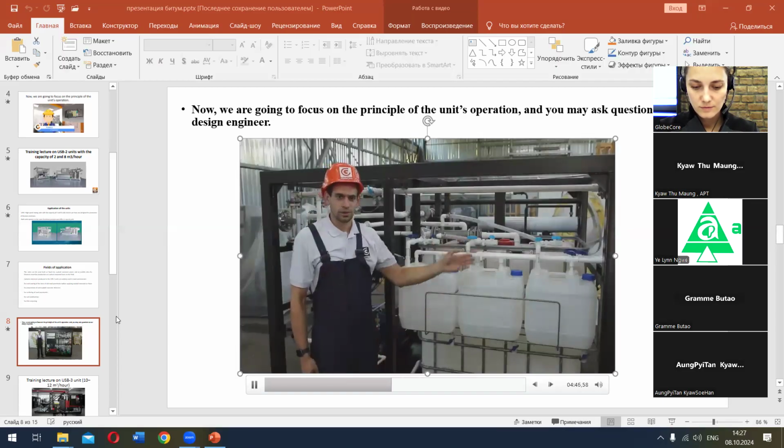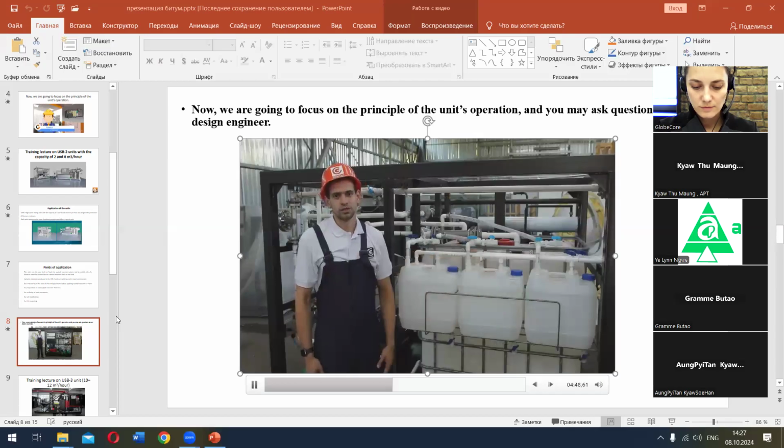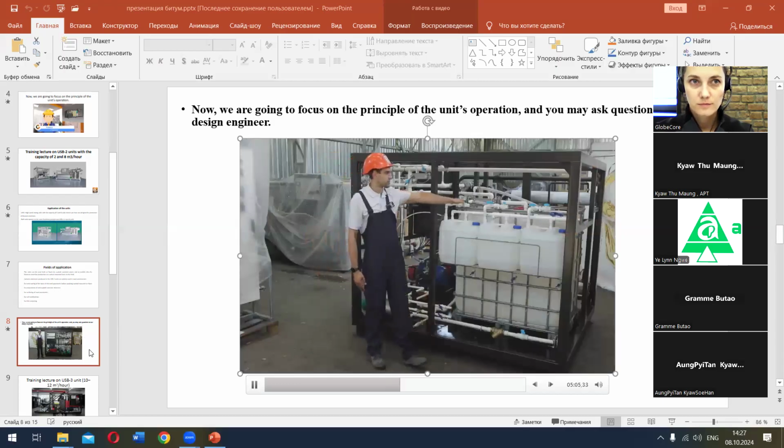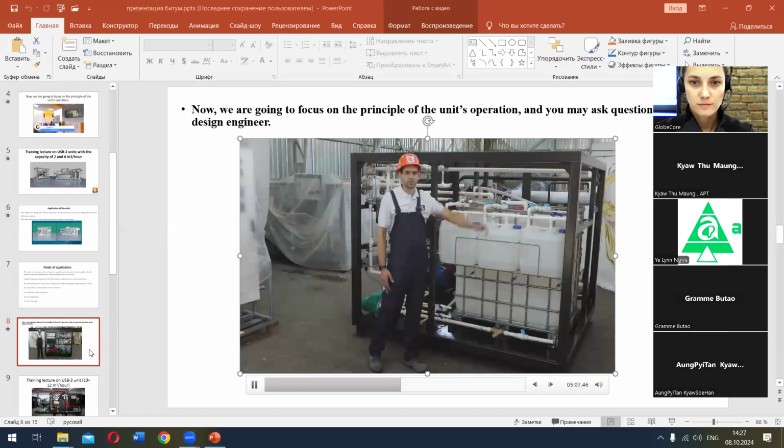Subsequently, the operator has the possibility to adjust the volume of acid used by means of a measuring ruler. We also use a manual pump to fill the remaining tanks with emulsifier and adhesion additive. Next, the blend pump is engaged. The water is supplied to the blend mixer where a vacuum is created.